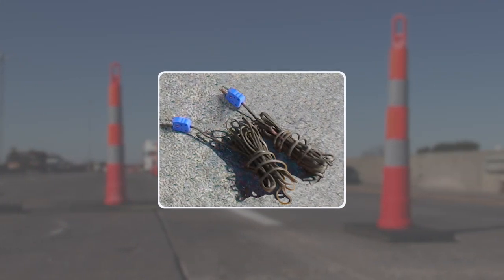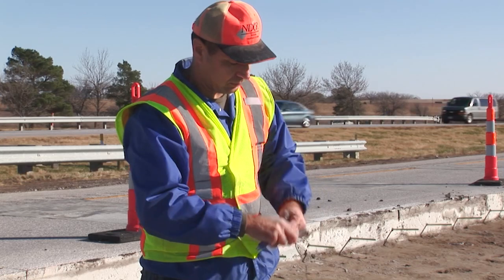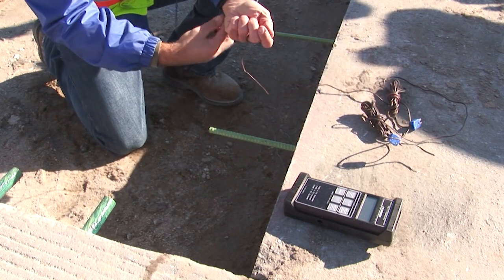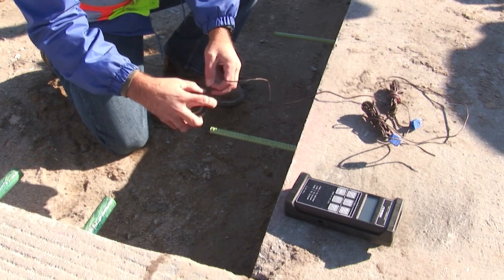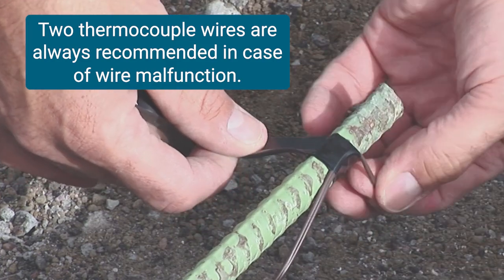It is also recommended to install 2 thermocouple wires to monitor the concrete placement. Both wires may be installed at the same location at the beginning of the day's placement. Another option is to place 1 wire at the beginning and 1 wire at the end of the day's placement. 2 thermocouple wires are always recommended in case of wire malfunction.